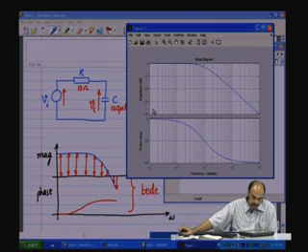So, that is how the meaning would be of this particular gain waveform. And look at the phase, that is, there is a phase shift between the input and the output. If you give a particular waveform of some particular angle with respect to the input, the output is not phase shifted near DC, but the phase shift is gradually increasing in the negative direction because it is a capacitance, and ultimately goes to 90 degrees when the frequency becomes pretty high.